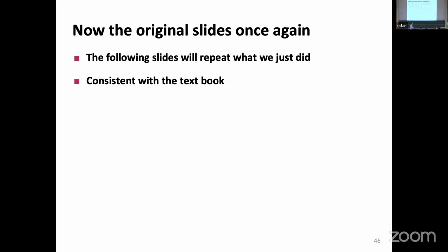I have the instruction. On the instruction, I have the read1 and read2 addresses. So I go to the register file and I pick those things up. I go to the ALU, and the result goes to the third register for us. And then I write back to this register.